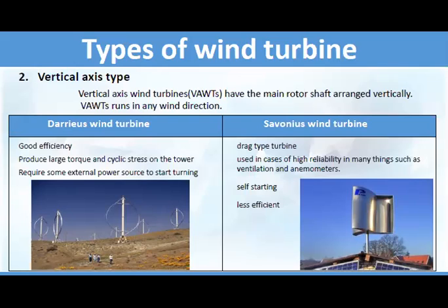When a turbine is mounted on a rooftop, that means the top of the building, the wind generally is redirected over the roof, and this can double the wind speed at the turbine. If the height of the rooftop mounted turbine tower is approximately 50% of the building height, it is near the optimum for maximum wind energy and minimum wind turbulence.